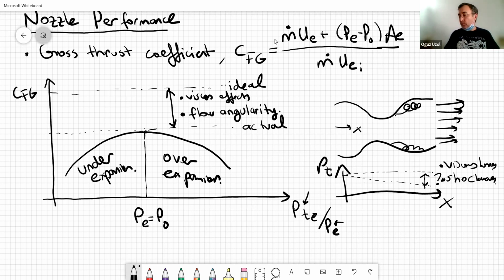For some propulsion systems, we can manage this flow angularity by playing with the nozzle, either vectoring it or changing the area. But for some propulsion systems, we don't do anything. For example, for space flight, rocket engine nozzles do have thrust vectoring capability. In fact, this is how SpaceX can land all those systems back on Earth, by thrust vectoring.